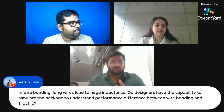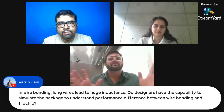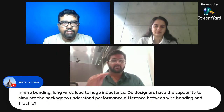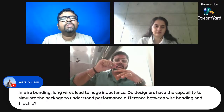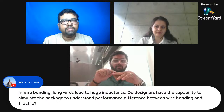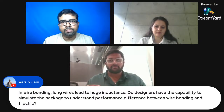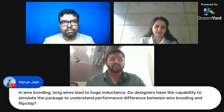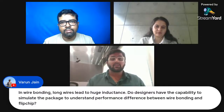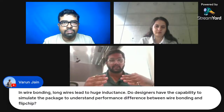Okay. So generally, wire bonding is majorly used for the memory devices, as far as I know. Memory devices, because we need to do the stacking, and then from the bond pads we need to take out a single wire and connect to the other bond pads, or some sort of bonds we have to make. So wire bonding is very much useful in that way. But at a flip chip level, we can do the 3D stacking. So everything is replacing at its own level.